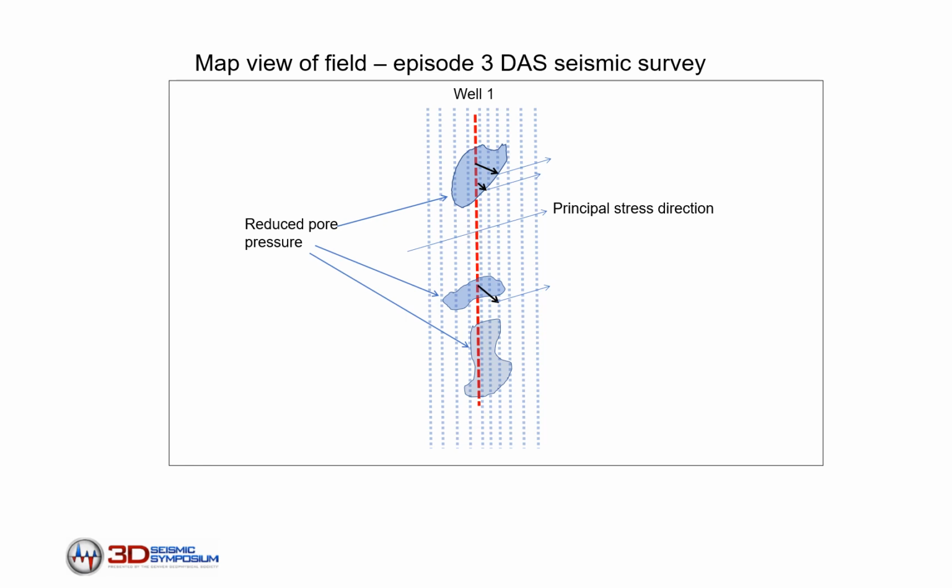But probably more importantly, if we're going to drill a nearby well, a new well, we want to be sure that we take these pressure drawdown zones into account as we plan the fracture, as we plan the completion procedure. We don't want to just go pumping a bunch of fluid in here because we're just inviting a frac hit on this well, because it's well known that fractures are drawn toward lower pressure or lower stress regimes.